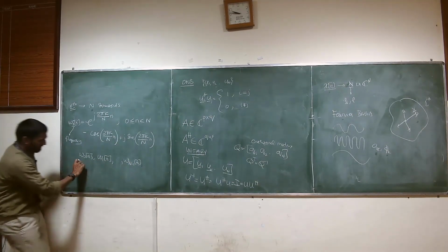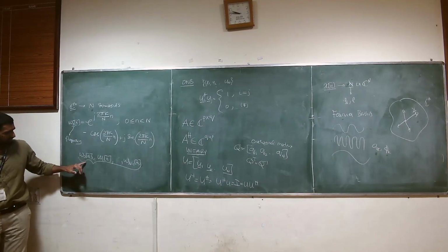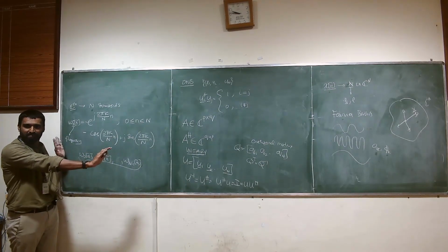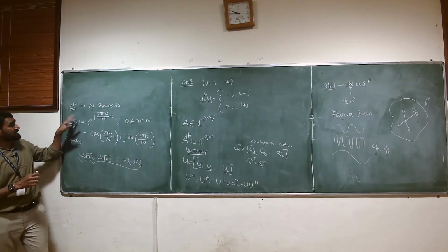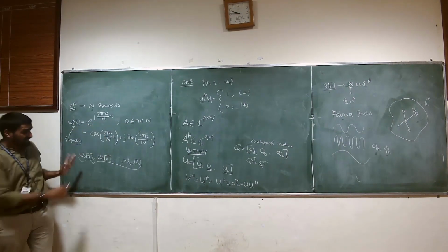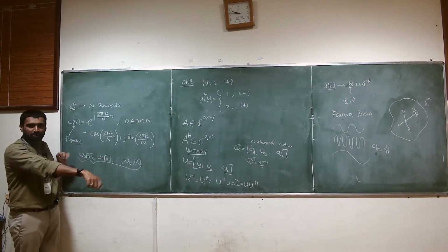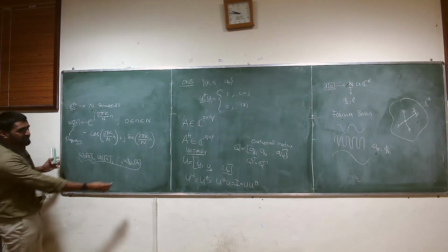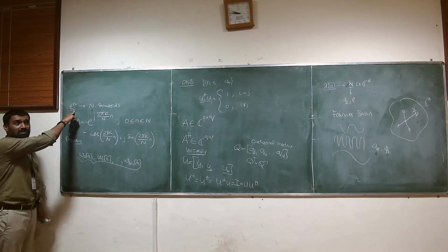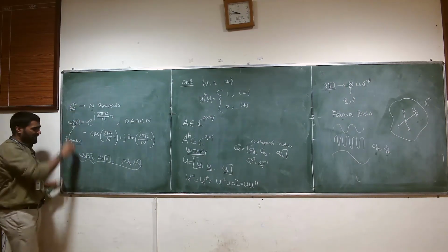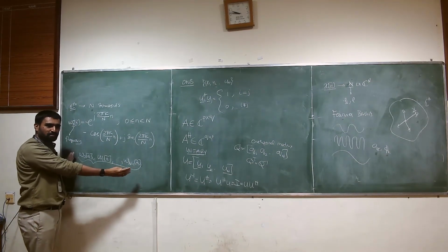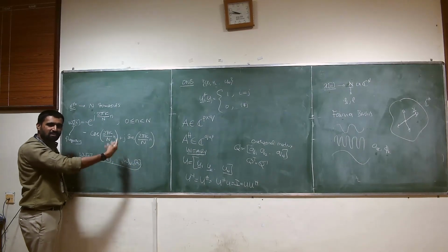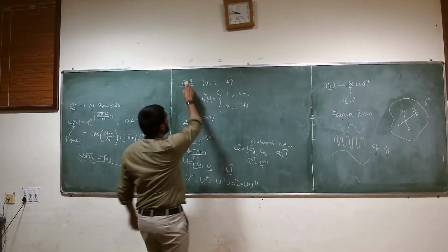So we have these N possible sinusoidal signals, and each of these represents a sinusoid of different frequency. That means for finite duration signals of length N, there are only N frequencies that are possible, nothing else is possible. And that's what I've written here. It seems like a nice coincidence, right? We're talking about a vector space of dimension capital N, and there are only N sinusoids that are possible. Sounds like this might have to do something related to the basis for the vector space, and in fact it is.